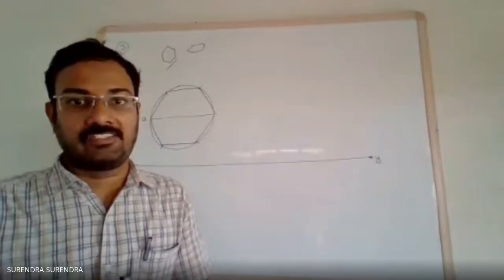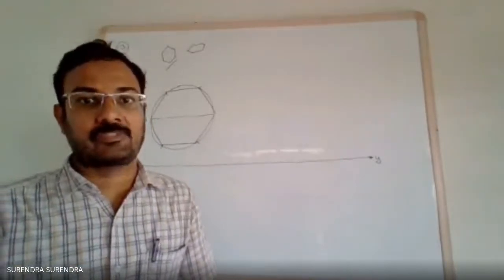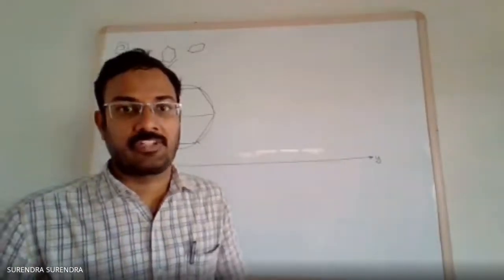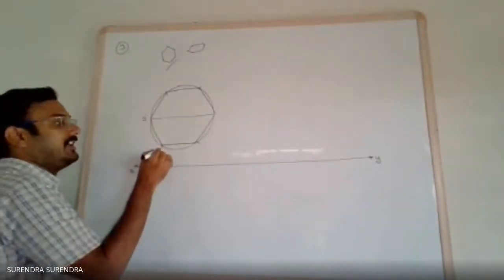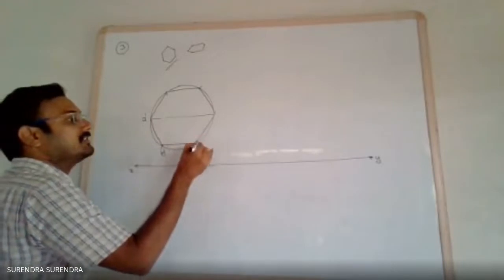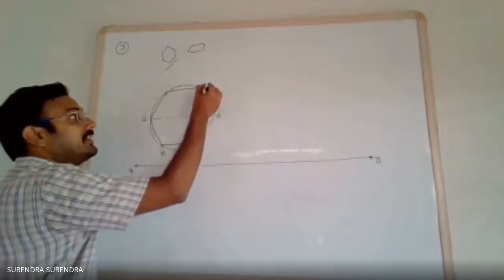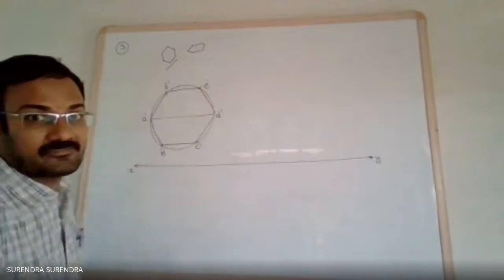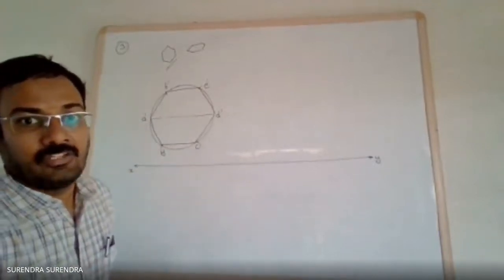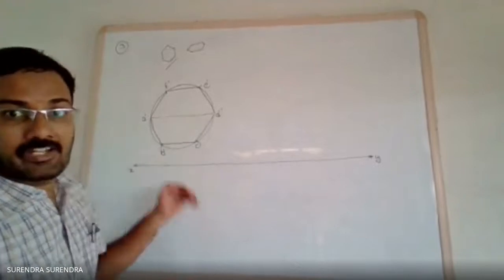The circle and the diameter line must be as light as possible, as those are only for construction. Now, name the corners as A dash, B dash, C dash, D dash, E dash, and F dash. Now, for drawing its front view.